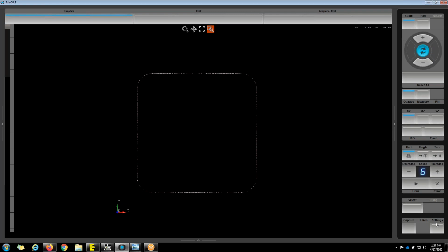Now, because we are generating a surface, and if we think about what we've done here, we created another surface that's going to taper inward. As we work in towards that pocket, these radiuses are going to get smaller as we get towards the bottom because we're kind of collapsing in on ourselves. Likewise, if we had programmed it the opposite of that, where we were getting larger with our surface, those radiuses would start to get a little bit bigger.